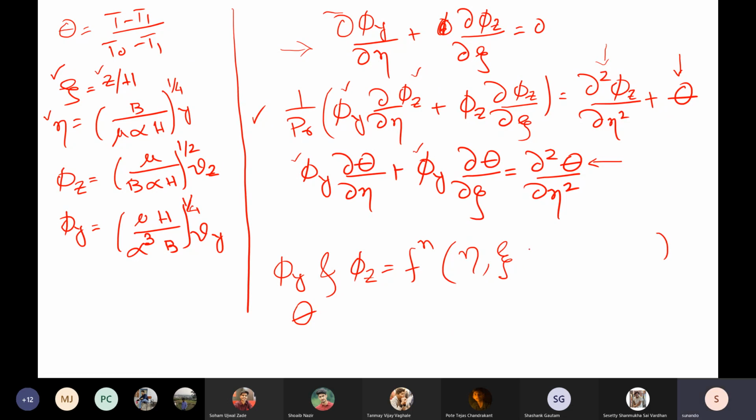Are we missing at least one more? So, Prandtl number. It has to be Prandtl number as it appears in the equation. Now, is it related because of the Prandtl number? We know that the flow in the case of free convection is rather slow. So therefore, the terms in which Prandtl number appears, the left-hand side, will generally be rather small.